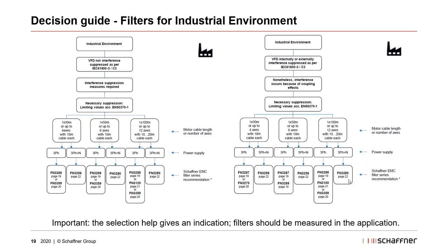What's important in this selection guide is that it gives an indication. In general, our filters are tested with different drive setups for different cable lengths and with different numbers of drives, but we cannot test everything. This is why, in general, it should be measured in the application to see if it fits the general limits you want to reach.